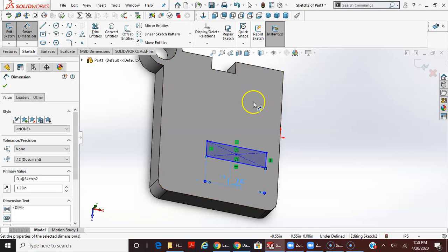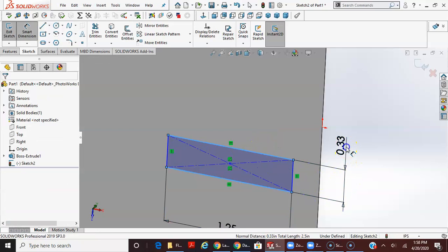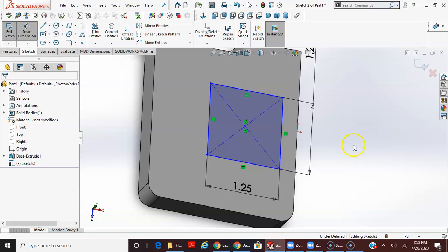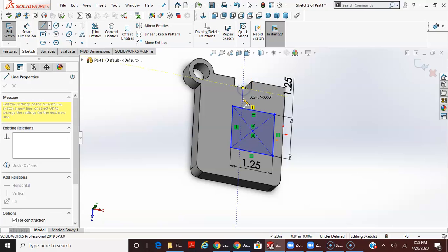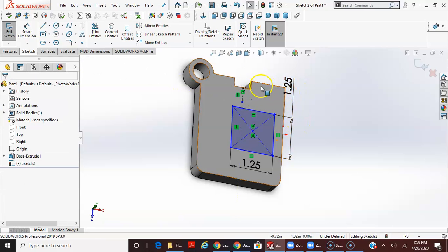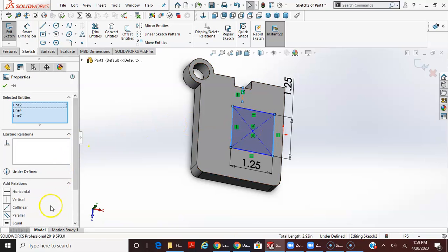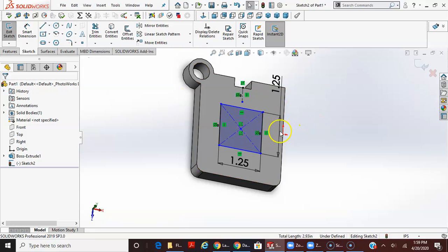1.25 off the drawing. And then the same thing here. Instead of dimensioning off of a line length, I'm going to dimension off of this edge to this edge. This is shown as 1.25. And then I'm going to add a center line or a construction line here from this midpoint. I'm going to make this construction line, this edge, and this edge symmetrical. So it is constrained now.